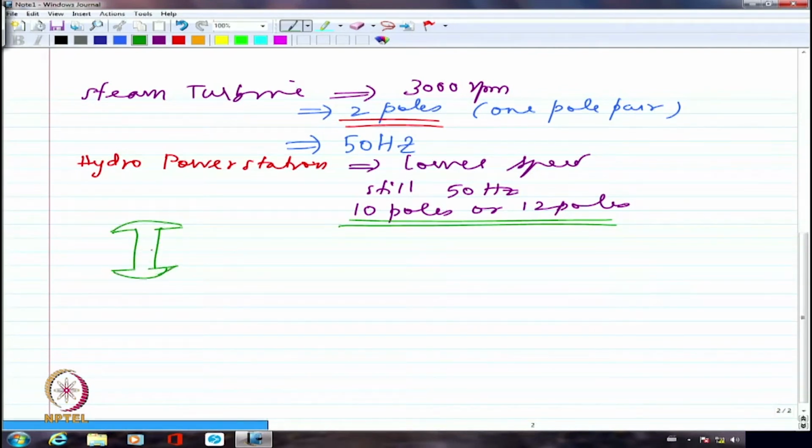Let us say this is my rotor with protruding structure. This is the shaft, right? So I'm going to have probably north pole here and south pole here. If it has a protruding structure like this, I will have a huge amount of centrifugal force acting towards the ends. If they act on the protruding surfaces, they can deform the winding. We don't want the deformation to happen, especially when they are working at very large speeds.